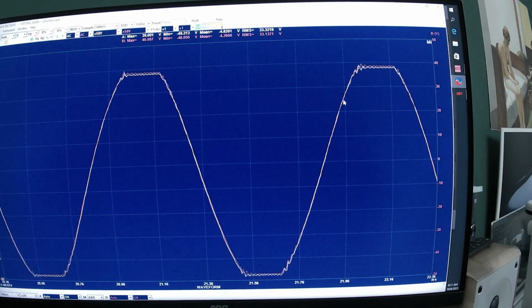So what do you think, guys, about the power capability of the TPA3255 at the 8 ohm load? That is a 1 kilohertz signal, maybe 10% distortion, 136 watts per channel. Well, if you ask me personally, that's really awesome.